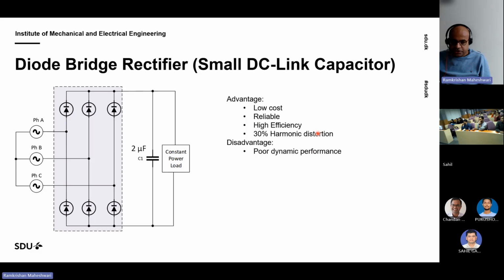And then high efficiency. I talk about the system efficiency here because if you have less harmonic current from the grid side, then you have low losses. So you save some losses. There is research done, and they claim that up to 8% losses will be reduced if we go for a unity power factor rectifier in the distribution lines. So not in the system, but in the distribution line. So you can save quite an amount of energy. Then I talk about low harmonic distortion.